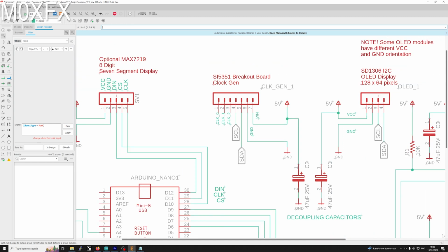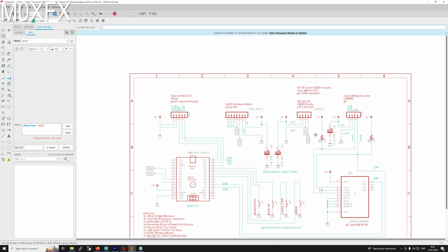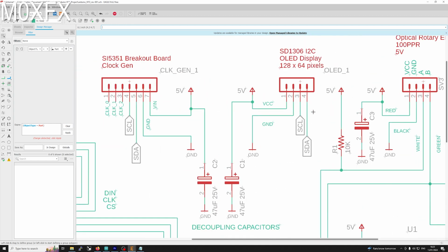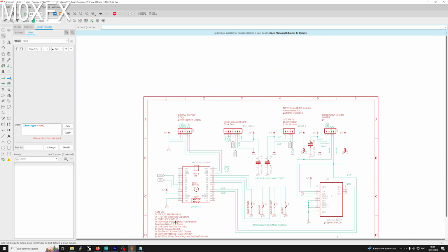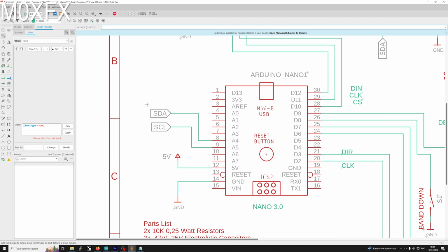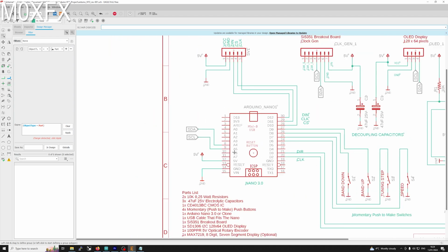There's a few other parameters that we can send up there. And there's the OLED display. We simply tell it what we want it to display, and all the information comes up via here. So SDA is connected to it. They're all common together. So these are literally daisy chained along these two devices from pins 4 and 5 on the Arduino.